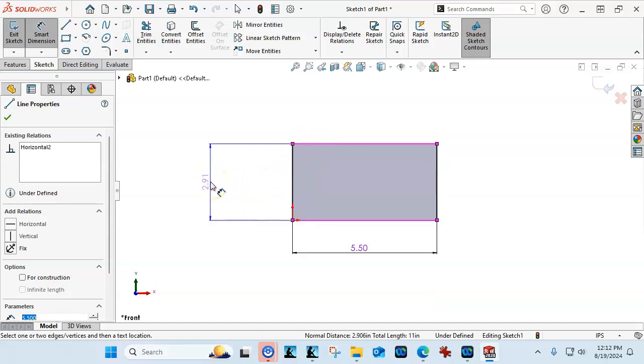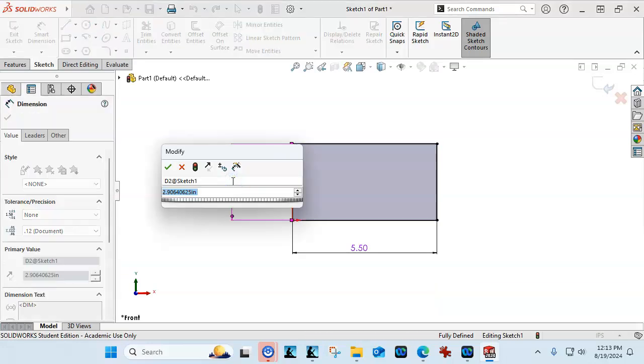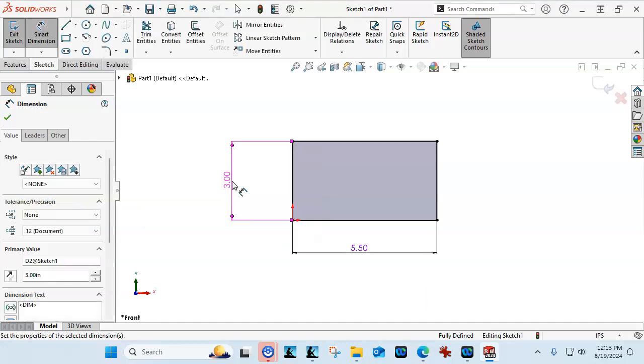because sometimes there's a gap in there, sometimes there's other geometry that might interfere with it, so we can pick between two objects. Again, I need to left click and place the dimension and then enter the value, and when I hit enter, it stretches.